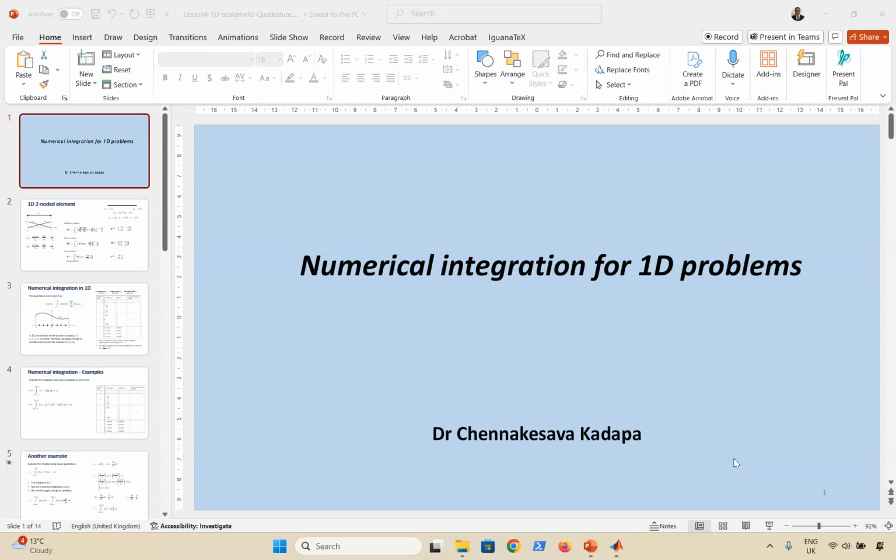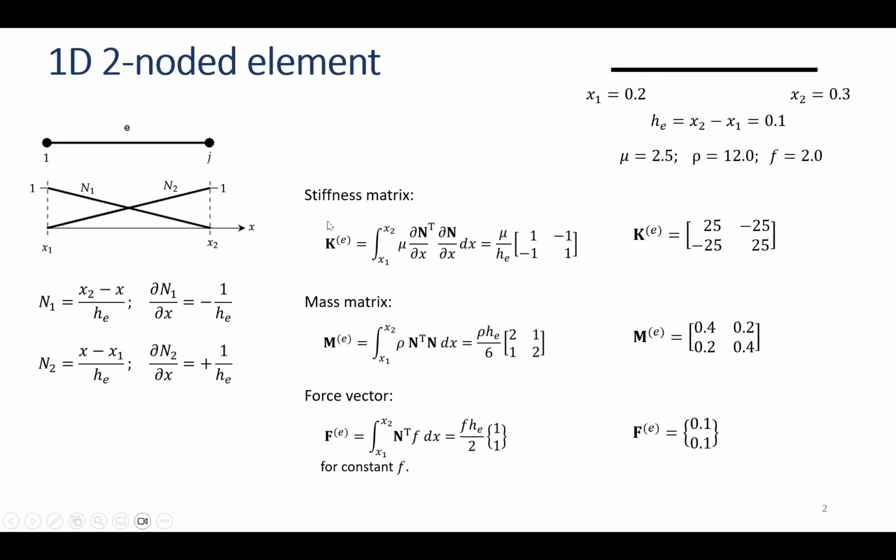Hello again. In this video, we are going to look at how to apply the numerical integration method for calculating the element quantities, that is element stiffness matrix, element mass matrix, and element force vector for a 1D two-noded element. So we use the 1D two-noded element, and for this element we know the basis functions.